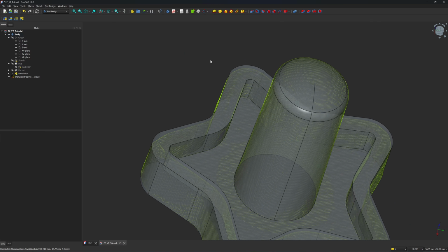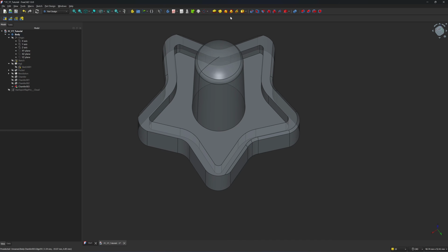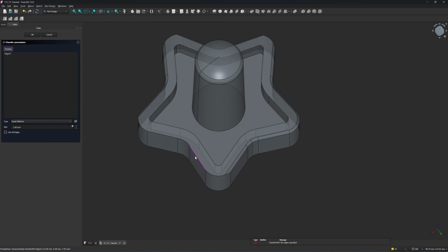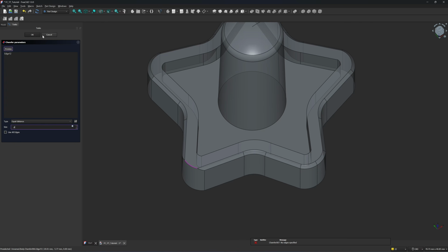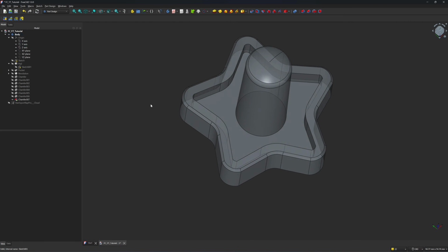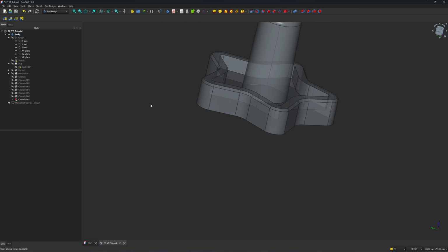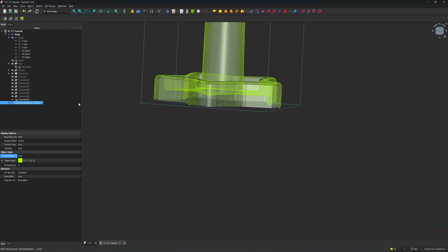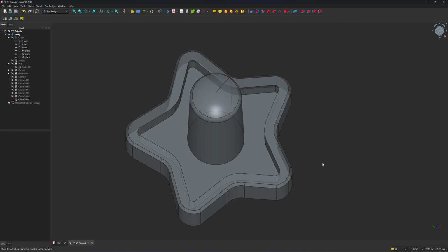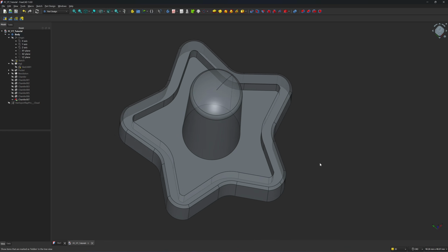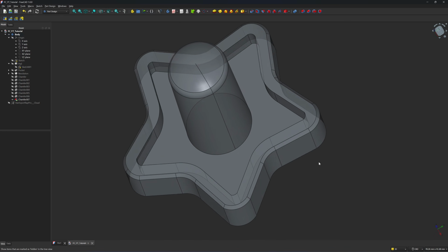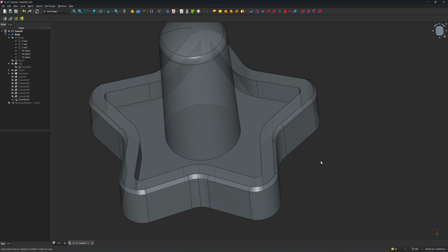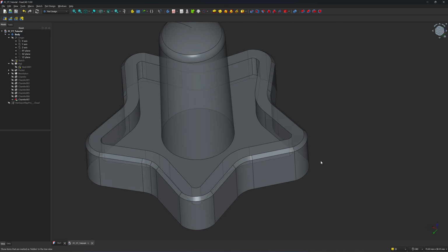To do the chamfer, I click here. Chamfer 0.6. Okay. So a chamfer with FreeCAD doesn't do very well. With FreeCAD, it's a bit difficult to do a chamfer when you have a mixed curve and straight line. So there are still bugs that need to be ironed out.